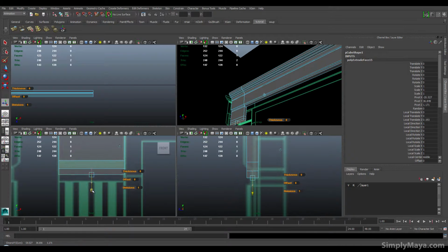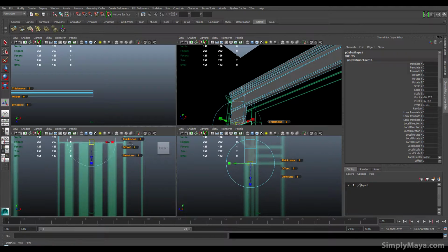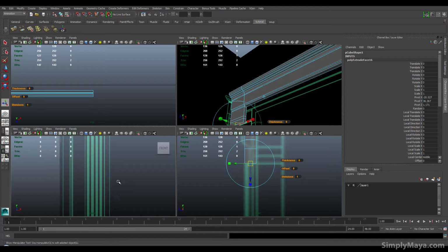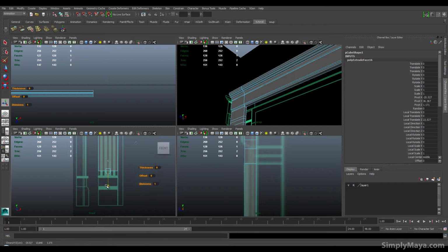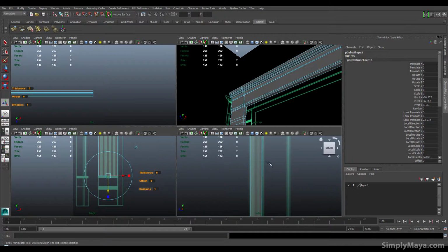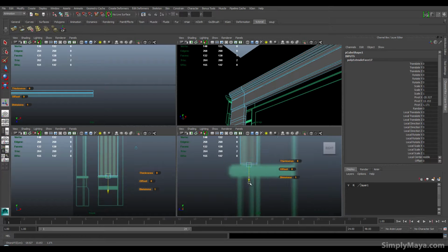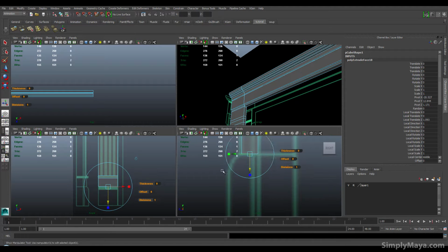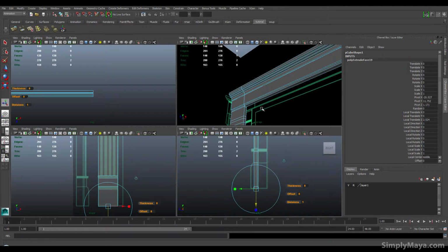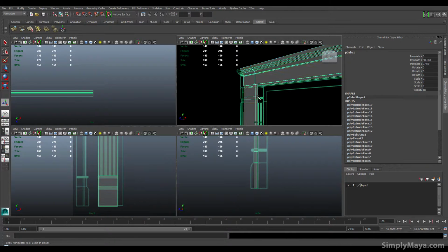Okay, so I'm going to need a part I can push backwards. So G, and I believe the next mark is all the way down here. It is. Alright, then we come to a kind of lip, I believe. Yep. So G, extrude, so we can create that lip. G again, keep going down, and we'll need to create this. So G again, once more. And there we go. So this is basically a basic extrusion modeling technique.